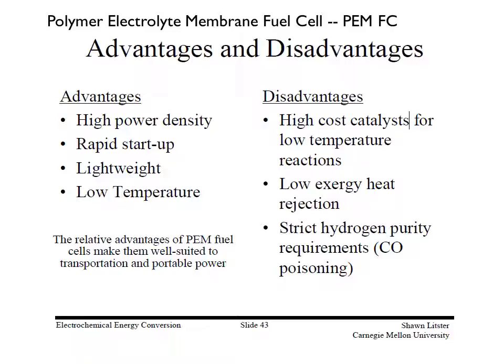And so you've got to have some kind of compressor to have a recirculation loop, which will drive thermal energy out of the PEM vehicle over to some kind of radiator. So not only do you not get to do any work with that thermal energy, but you actually end up having to spend work to get rid of it.